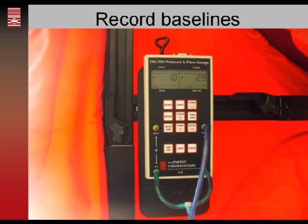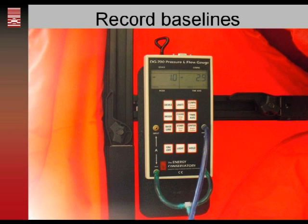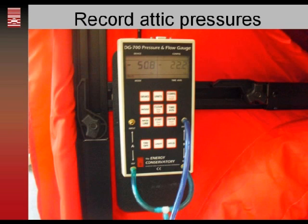So we've changed our house pressure from 1 to 50.1, so we've changed it by about 50. And now our attic is at -22.2. Baseline was about 3, so we've changed it from about 3 to about 22. So we've changed it by about 19 pascals. So our attic pressure number in this case is about 19 pascals.